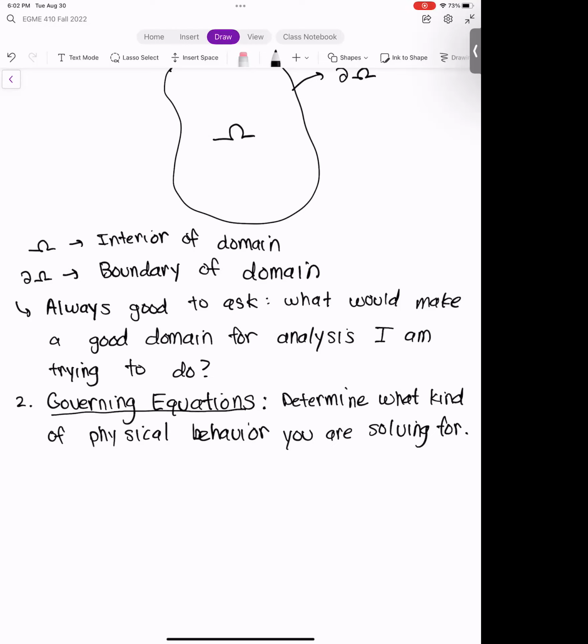And even though I call it governing equations, you don't actually go into ANSYS and type out the differential equation, right? And so that was not the experience that we had last Thursday. The form that this usually takes in software like ANSYS is that you choose the type of physics that you want, right? If you remember, one of the first things that we did last week in the workbench was that we selected the type of simulation that we're doing is a static structural simulation, right?